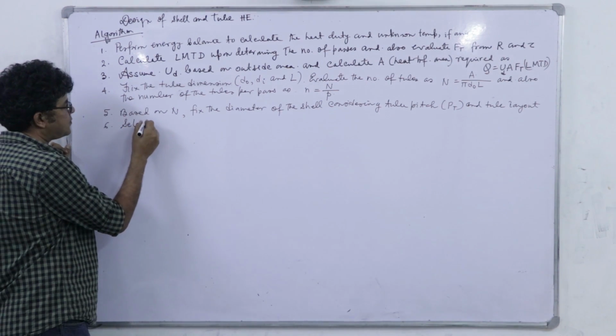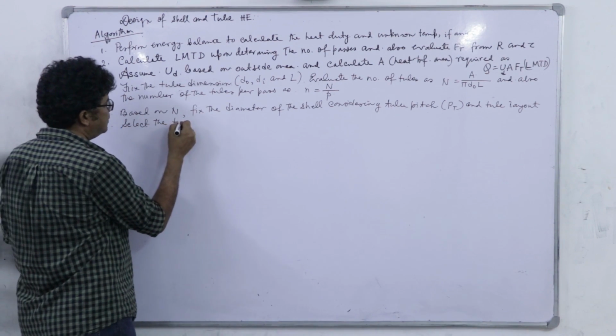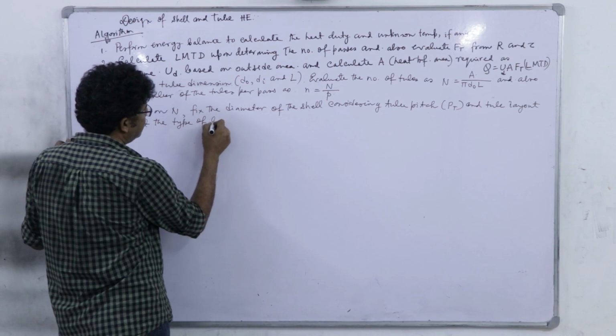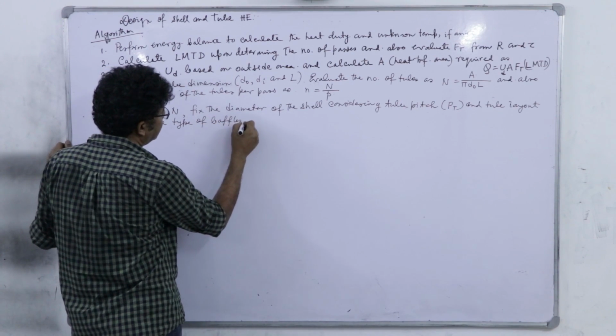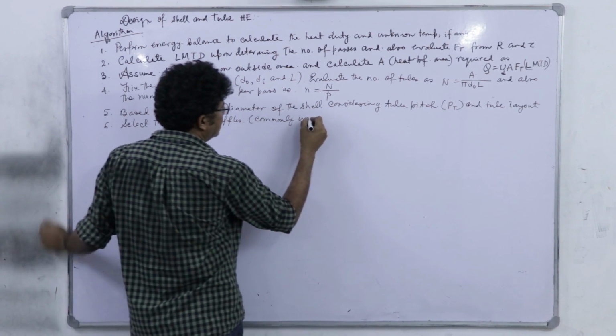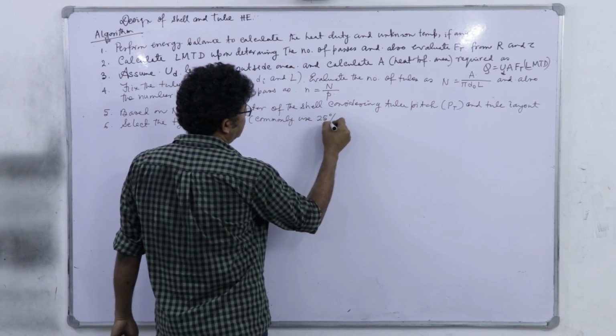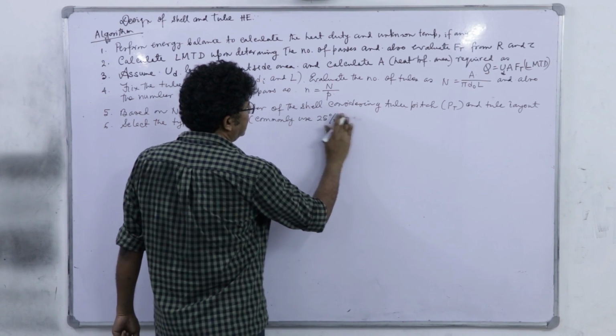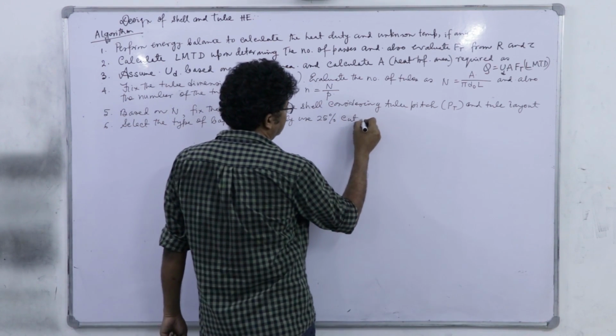Select the type of baffles, commonly used 25% cut segmental baffle.